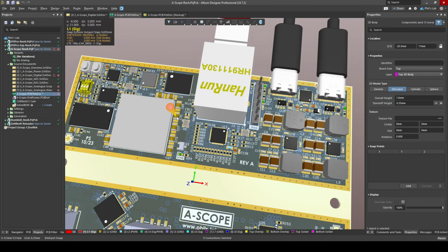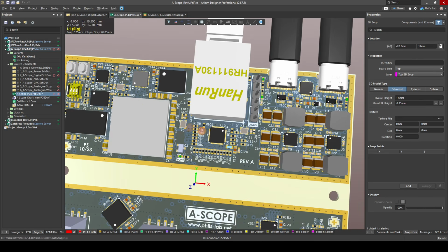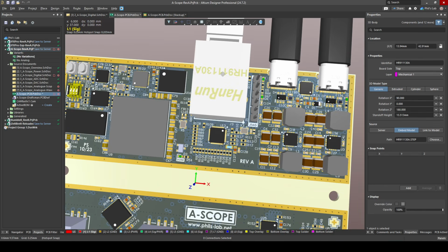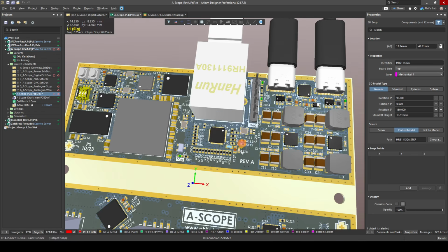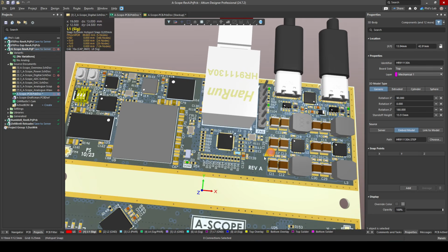But with this stack up in mind, knowing that we'll be routing predominantly on layer 1 and layer 6 as controlled impedance, 50 ohm single-ended, 100 ohm differential lines, we can get started looking at the layout and routing. Again, my MAC is on the left-hand side, physical layer in the center, and RJ45 connector at the right at the top above the physical layer. Because we're using a MagJack, again, this makes the PCB design a bit simpler. If we're using external magnetics, if we have further isolation requirements, we typically might want to increase the distance between the RJ45 connector magnetics to the physical layer.